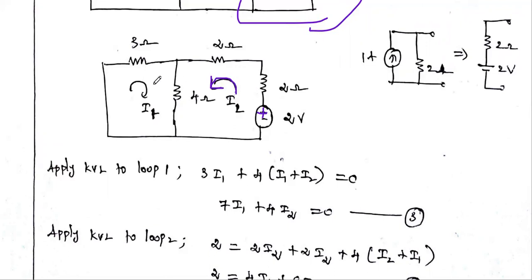Okay, now for this circuit we can't apply the inspection method directly, since in order to apply the inspection method both mesh currents must be in clockwise direction, but in this case one current is clockwise and the other is anti-clockwise. So you just write KVL, then you convert into matrix. That is the correct thing.